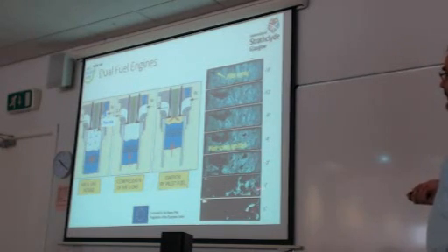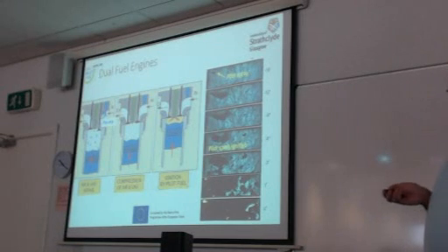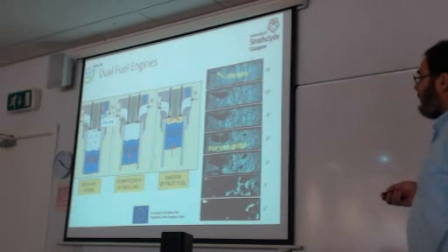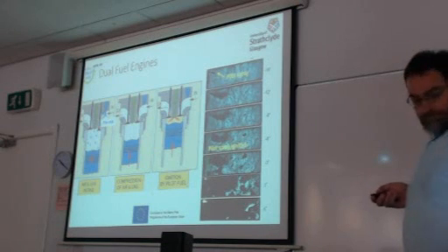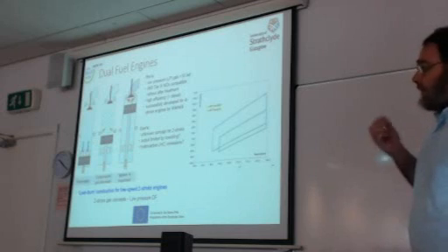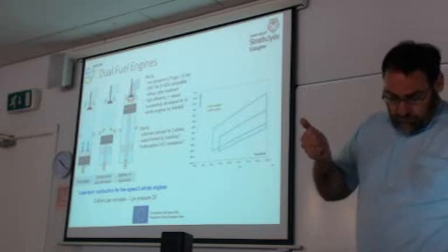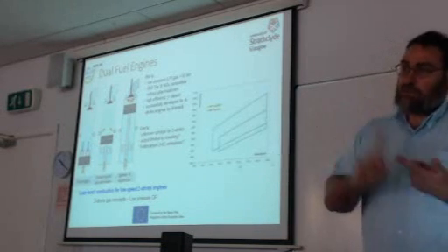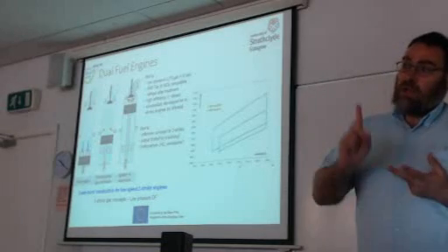So you can see that after the ignition, the combustion process is quite fast, and the whole mixture can be burnt within 3 to 5 degrees of crank angle. So a very quick process.